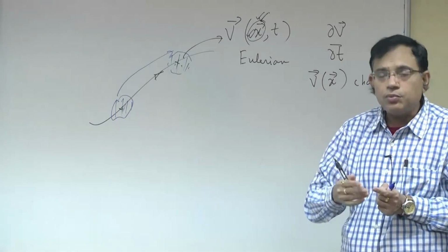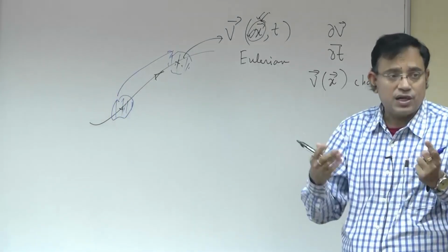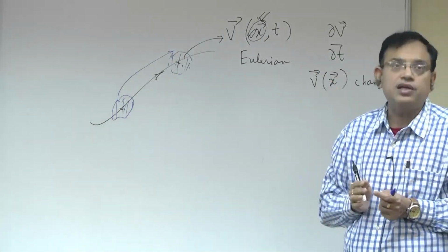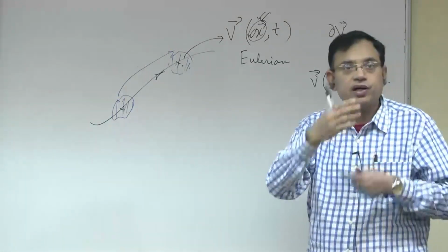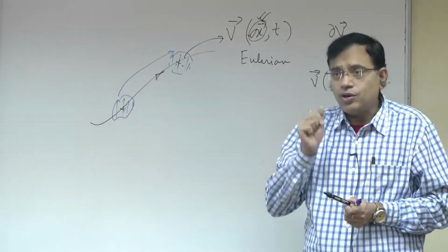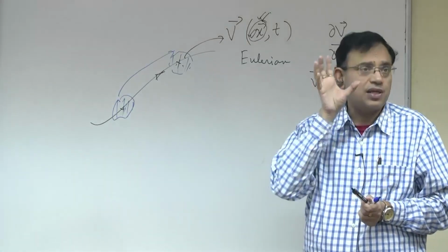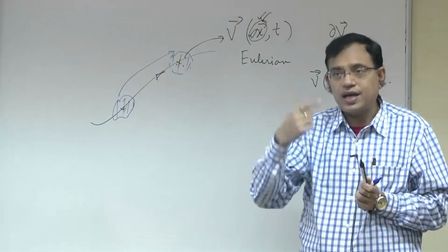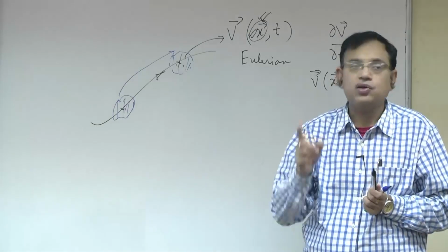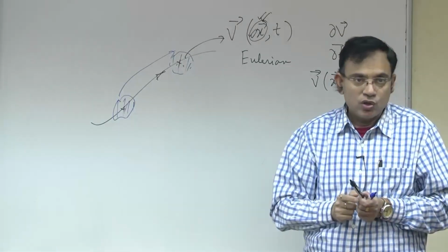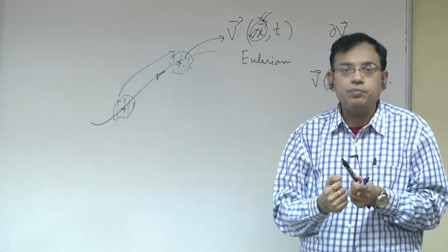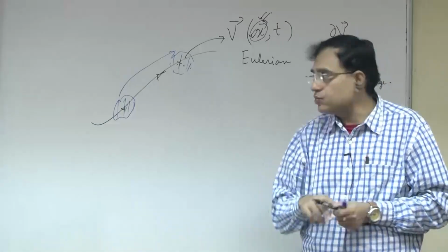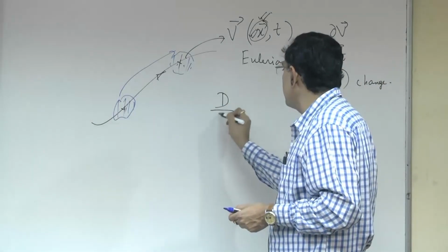Now, if we are talking about the rate of change of velocity, which is acceleration, acceleration is the rate of change of velocity in the Lagrangian description, where you have some particle and its rate of change of velocity is acceleration. If we describe that same concept with Eulerian variables, then the change is due to the time dependent change and position dependent change of an Eulerian variable. So, to bring this Eulerian variable based description into a Lagrangian calculation, we are introducing this total derivative, which is capital D Dt.